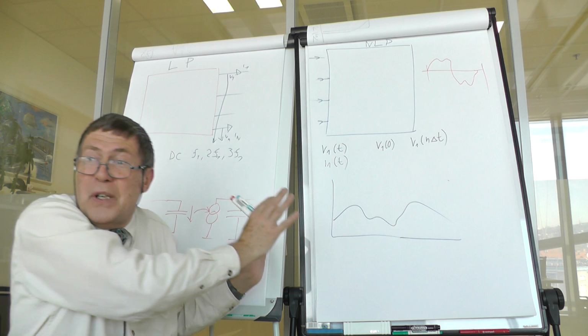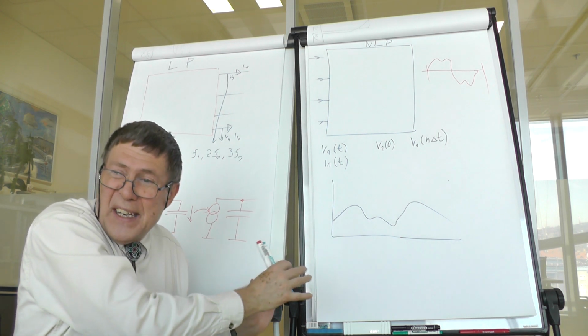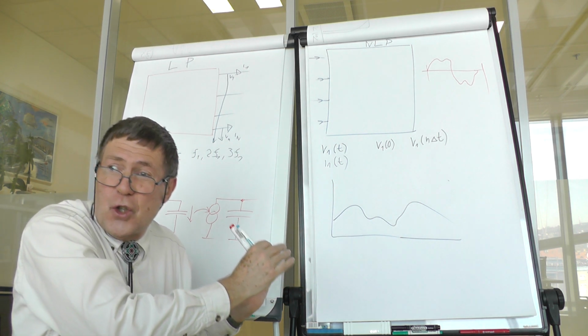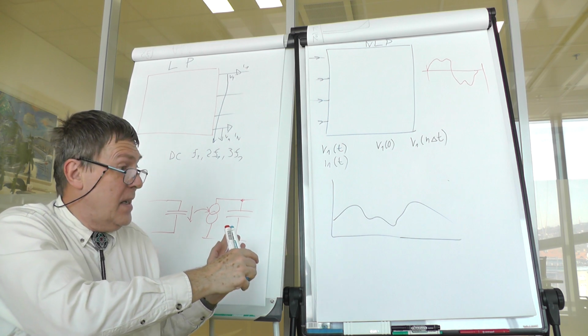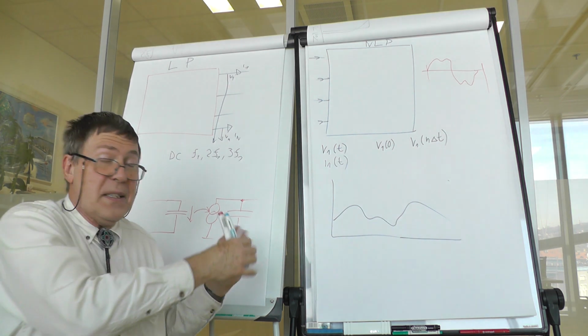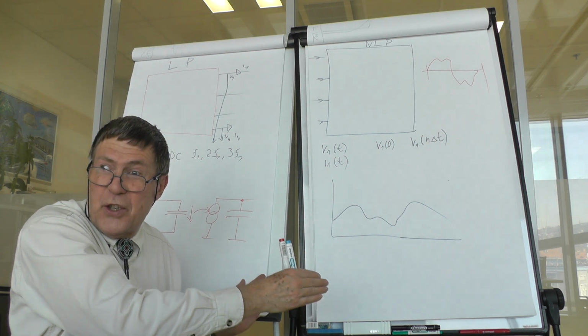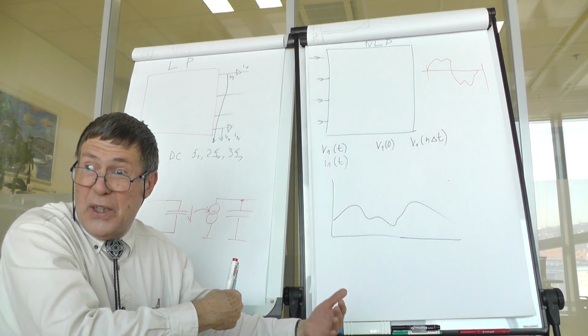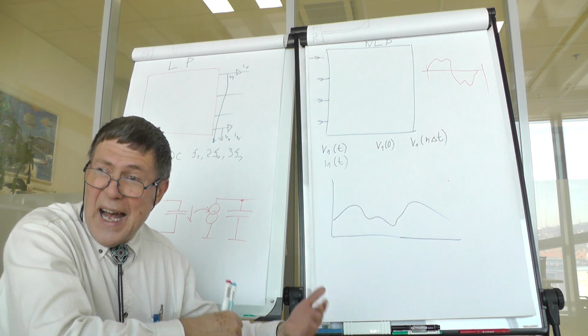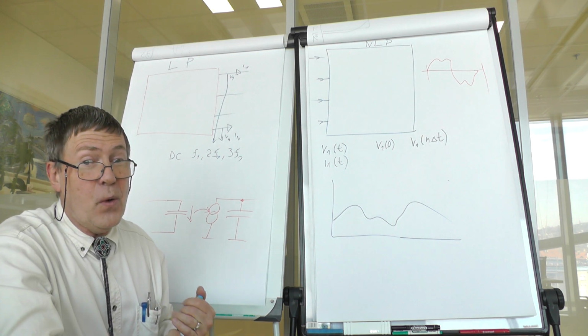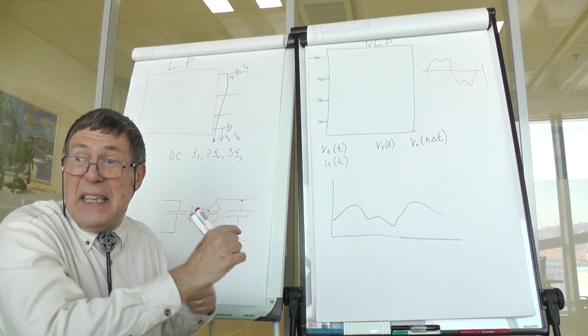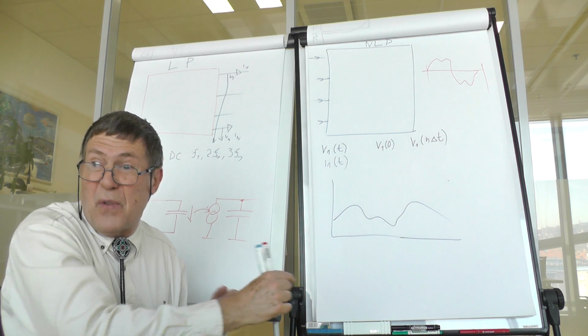So harmonic balance is a very nice method which shortens the time necessary for simulation by an order of magnitude. So it's very handy for circuits where you exactly know the frequency and it does not depend on the nonlinearity very much.